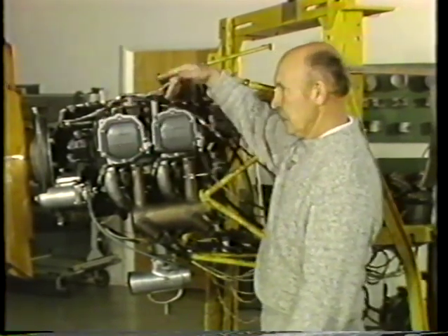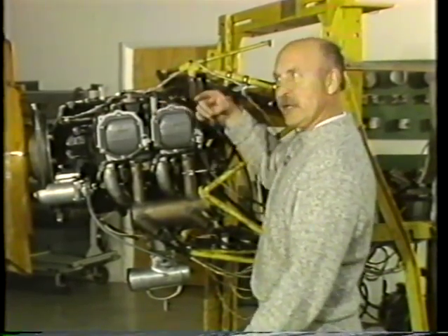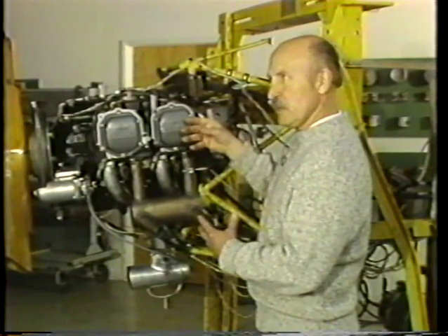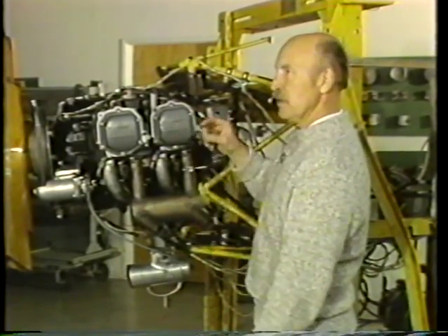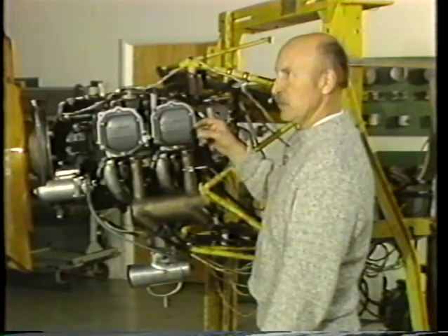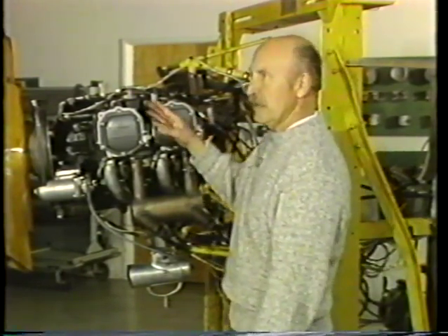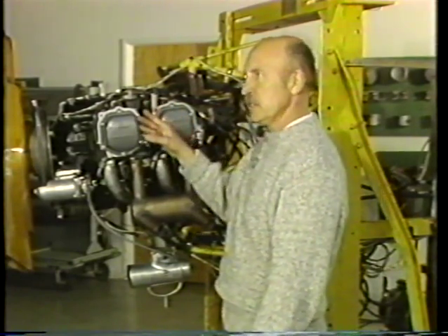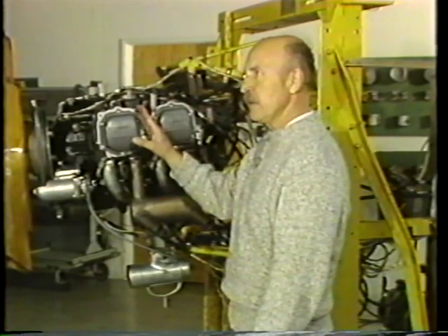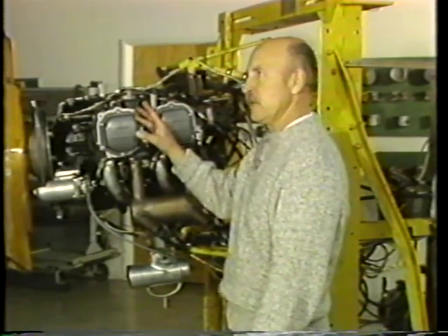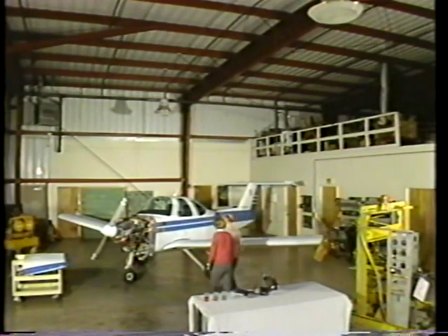And since we don't mix the fuel and air in the carburetor, here we have the fuel control unit that simply measures them. We eliminate that problem of the carburetor where the temperature drop occurs and icing would occur. The problem that is possible to run into with any carburetor or fuel injection system is impact icing when we have structural icing on the aircraft flying through freezing rain and that type of thing. Let's go over to the Skipper, Jeannie, and I'll show you how the ignition system works.